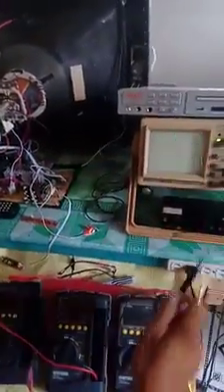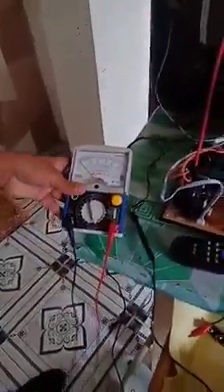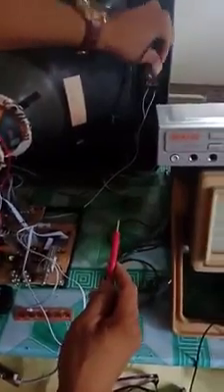You can also connect the negative of the DC voltmeter to the metals of this. The metals, no? Okay. How can we prove that the bare harness wire is connected to these three metals? By means of a continuity tester. Using this analog meter, set it to times 1 for measuring the continuity. Okay, we have here. Okay, it deflects, right? We have here.